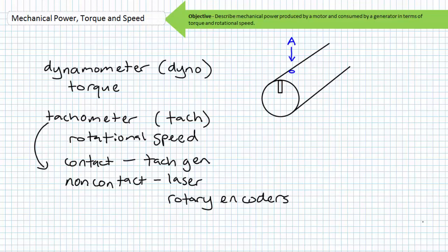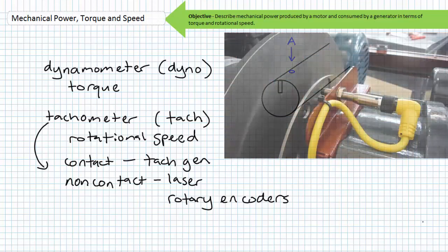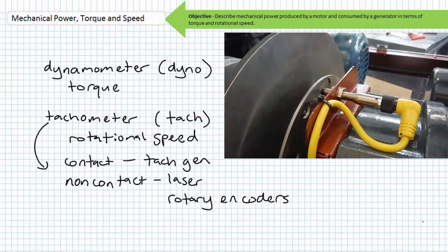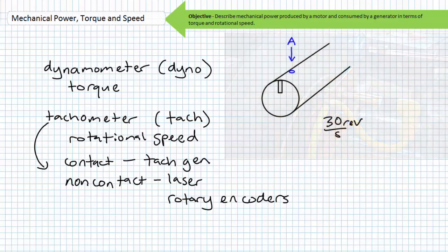Every time an indicator, the presence or absence of a metal object, passes through a Hall effect sensor, it detects that presence or absence and indicates it with a pulse, hence the term pulsar. If a single indicator on a shaft passes a sensor 30 times in 1 second, this means the shaft is traveling at 1,800 RPM. The single sensor scheme has a disadvantage though, because you cannot tell which direction the pulses are coming from. A single clockwise rotation produces the same amount of pulses as a single counterclockwise rotation.